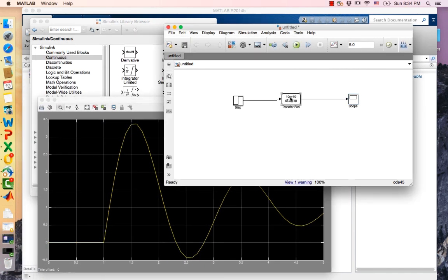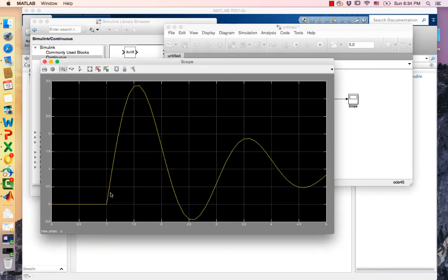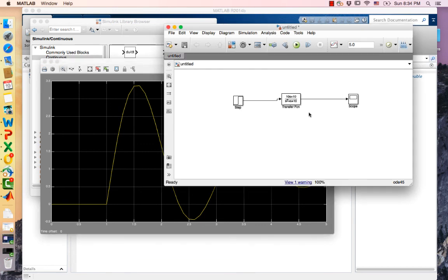This is like a derivative, and because it's a positive number, it can overshoot and go to lower. Remember, we did a simulation for one of the systems. We started with something. This is a zero effect. We have a negative zero, and this negative zero has a kind of derivative effect. So that's something you see.